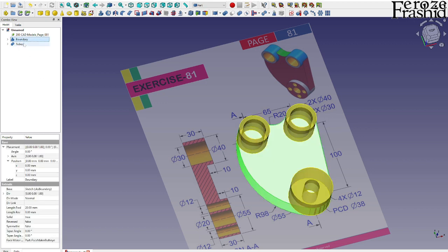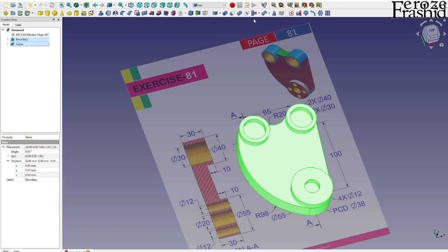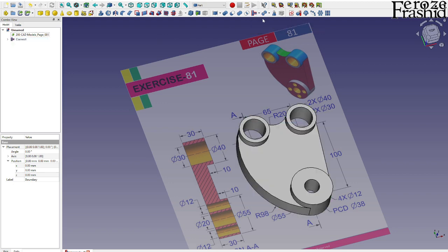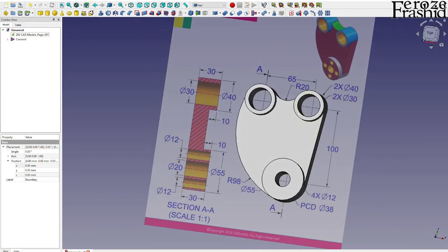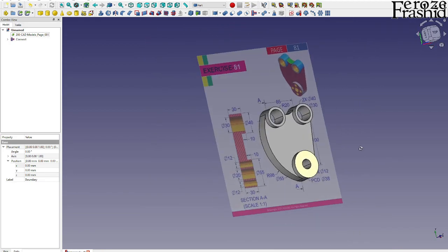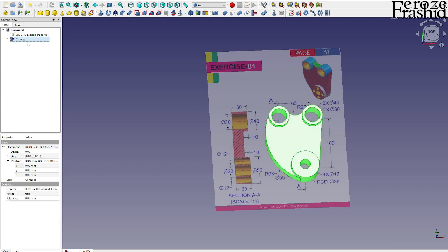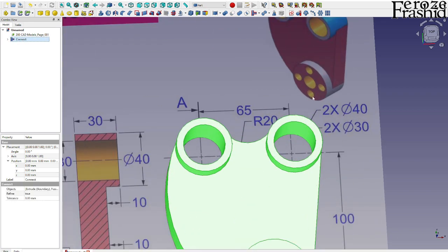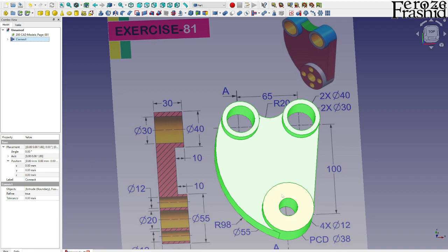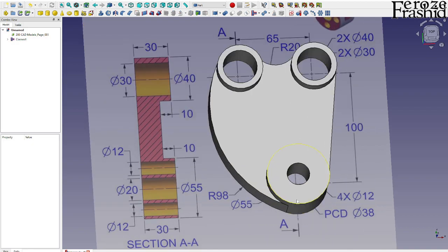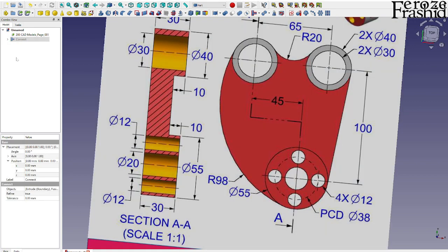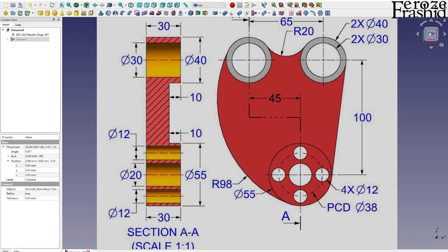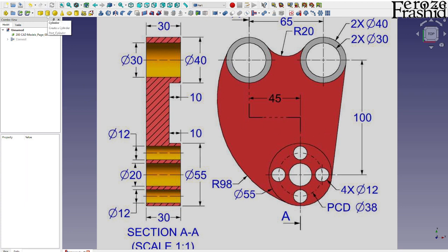So take the boundary and tube. Select these two and come here and say connect object. That will take care of the merging and deleting the inside part. Now we have one object, but we'll have to have these 4 holes at this lower revolver kind of thing. So let's go ahead and make that. I want to do that. So I'm gonna hide this for a moment, and I'll bring in a cylinder.